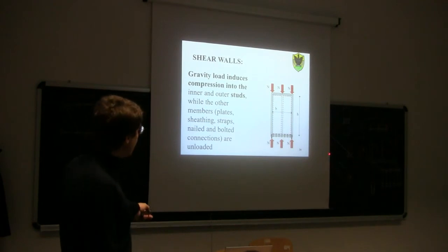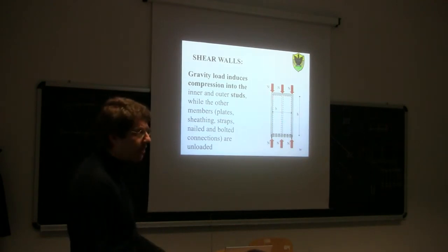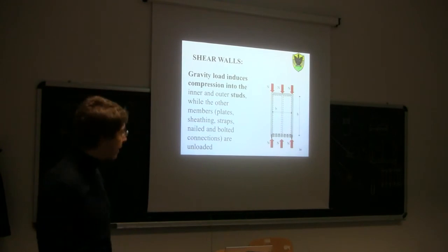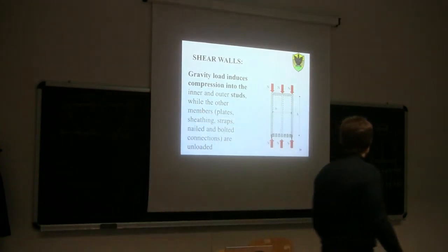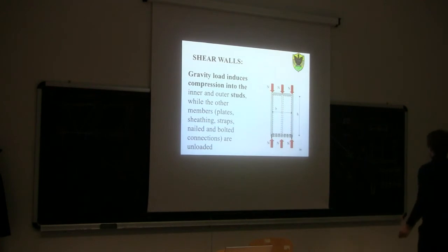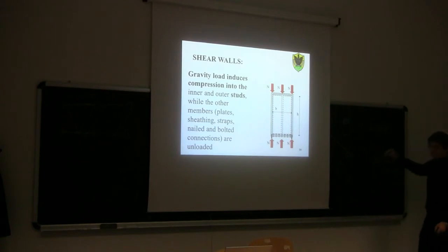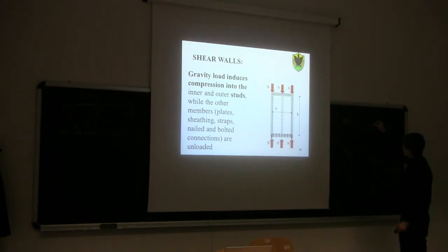So if we have compression parallel to the grain, what kind of verification do we need to do? Buckling? Yes? In which direction? Okay, let's put some axes here. So are we expecting these studs here to buckle in this direction here? Out of plane, or to buckle in plane, in your opinion?